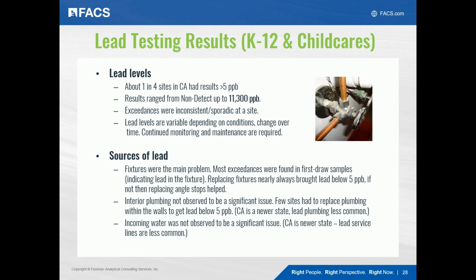As far as sources of lead, we saw that the fixtures themselves were usually the main source of high levels of lead. So when the sites replaced fixtures, that usually brought the lead levels down. Sometimes that didn't work, and replacing the angle stop, which is the shutoff valve, had to be done as well. But generally speaking, most sites did not have to touch any of their interior plumbing, and incoming water was generally not found to be a big issue.